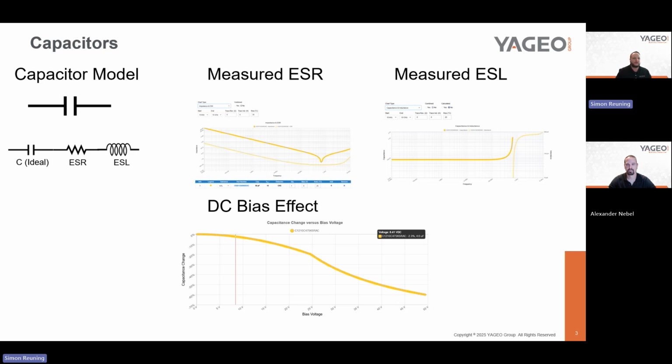I looked at the capacitor, I looked at the values, but the DC bias effect was messing up my end result. And so that's something that you really need to consider when you start looking at the capacitor, because the applied voltage in your application is going to have an effect on those capacitors as far as it goes for class 2 or less capacitors, the MLCCs. So if you are using MLCCs on your output for filtering, you really need to be considering that because it can really cause you some issues. They may not easily be solved unless you start switching to different technologies, and that's not always possible, especially if you're limited by space or voltages. So when you start looking at the DC bias effect, make sure that you understand it on the capacitors that you utilize in your applications.